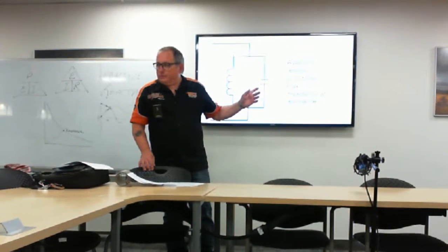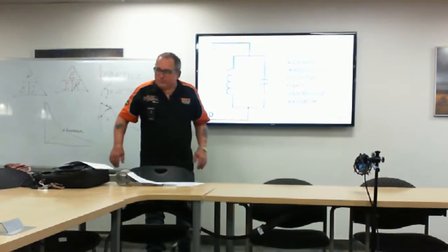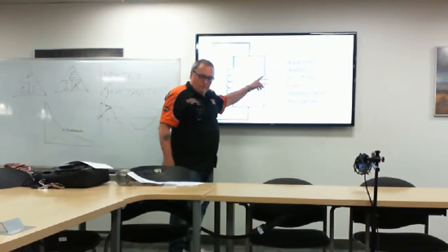My question really should have been, why are we doing this? Everybody knows the stereo system. Let's say you want the highs, the high frequencies, to come out. You would set the resonance there at the high frequencies by adjusting your capacitance, your little knob. You're adjusting that resonant frequency it is tuned for, so it'll only allow the highs to go out. You can also adjust it the other way to make only the lows come out.